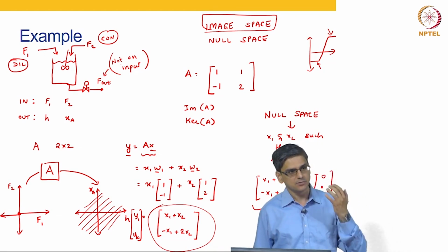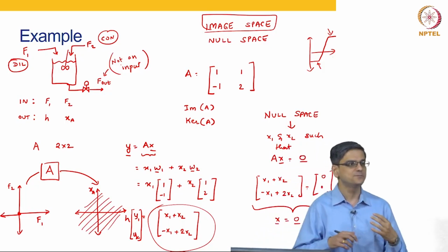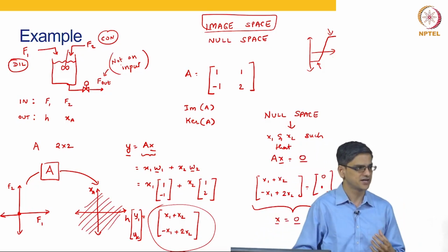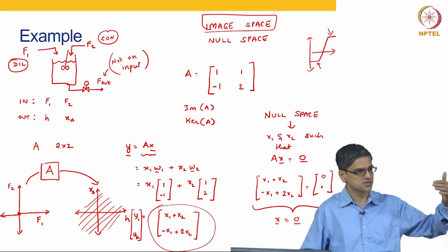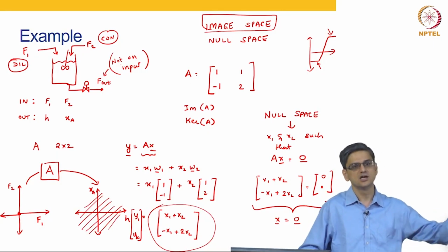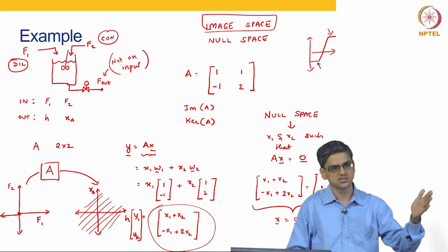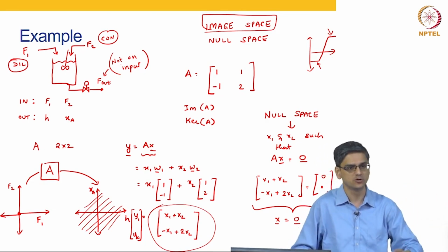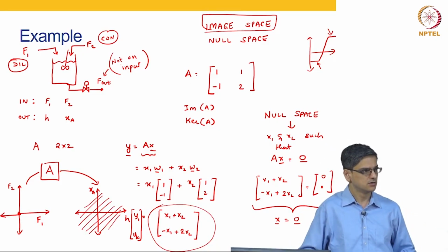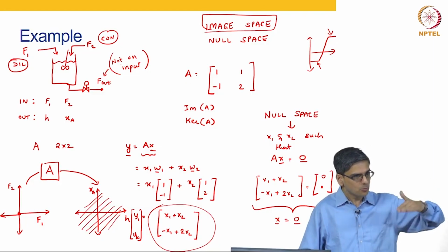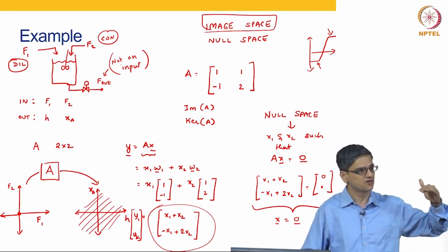At the same time, linear control is used for keeping the systems near the operating point. Let us say you have a reactor, the reactor temperature is 300 degrees Celsius, and your conversion is 80%, and therefore you get purity of the system to be around 0.7. You are going to go only in a small vicinity of that.